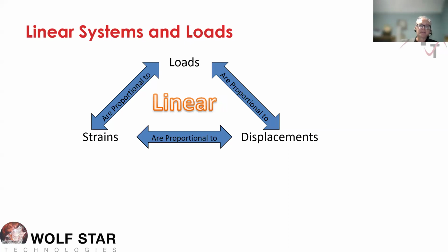We're going to be in nice nominal areas where the strain responses are remaining linear and proportional to the exterior loads. The loading can be as nonlinear as anything. It could be ramp loading, sinusoidal loading, even impact loading. That's okay. We just need that strain response to remain linear and proportional to exterior loads.